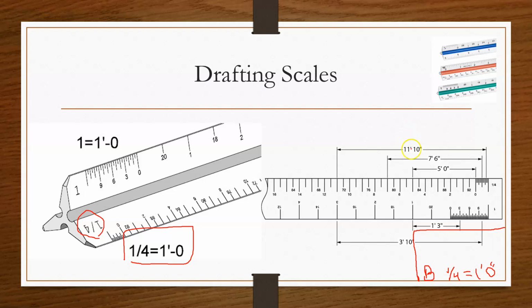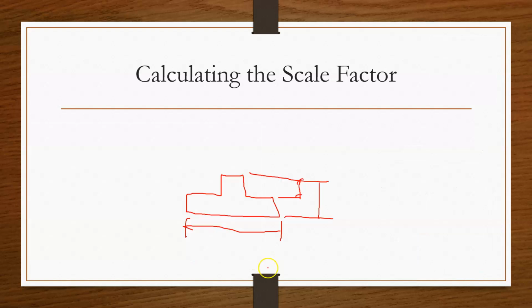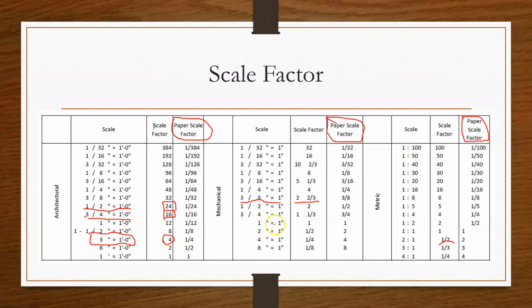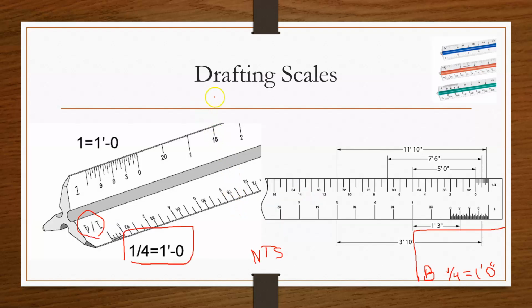Now, this is what I was telling you in the beginning. If in this title block here it has this dreaded word, NTS, now you might have to make a phone call, right? Because this just tells me that whoever drew this did not use a typical drafting scale. And that's all of these are: drafting scales that they have actually developed a scale for.